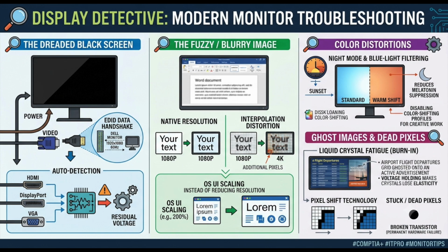A severely artifacting or flickering screen is visually alarming, and it usually points to a severe breakdown in the data pipeline. As always, you verify the physical cables first. A single bent pin in a connector can cause massive signal degradation. Right, check the hardware first.